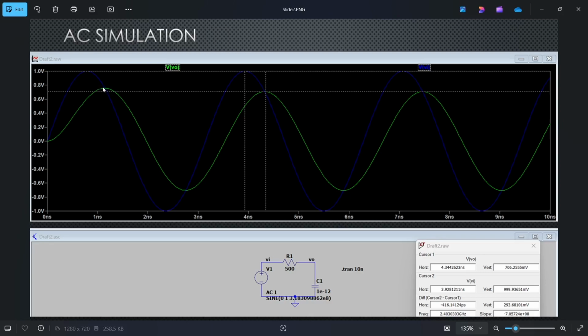the amplitude has been degraded, which if I measure it here, it's approximately 0.7 volt when I apply 1 volt at the input, right? Which is showing that actually we are at the 3 dB frequency of this low pass filter. But you also can see, because your input has a phase of 0, that in terms of phase, you have a phase displacement between the output sine tone and your input, right?